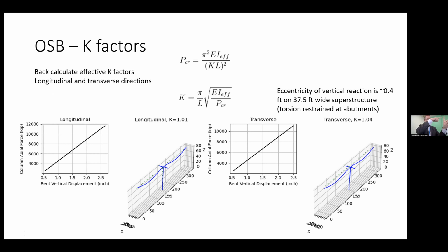So the statics thing is, you take the torsional reaction, and then move the force couple over to some equivalent distance. That distance is about 0.4 feet. So that torsional boundary condition is not messing things up unnecessarily. I think in practice, for the transverse direction, a lot of times that's assumed to be a flagpole, for a single column vent, in which case K is 2.